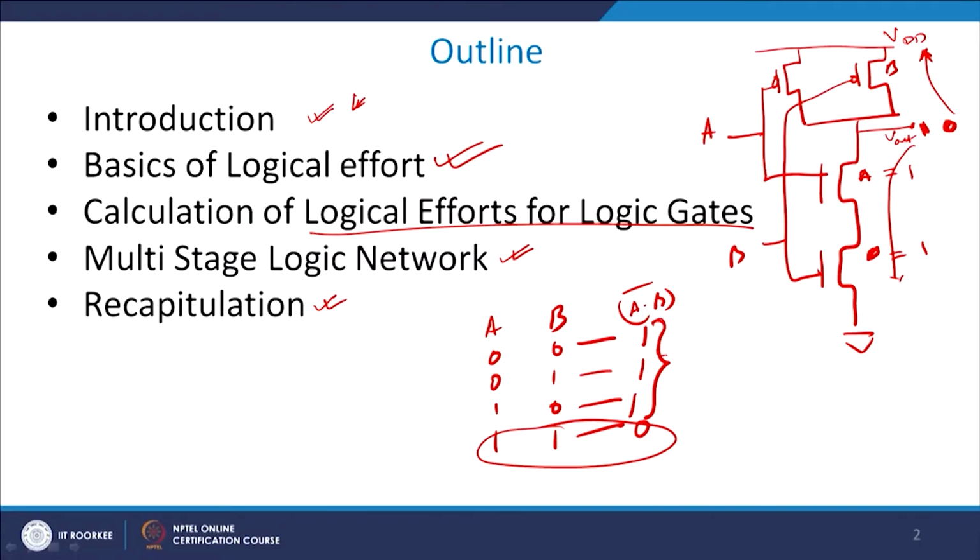So, therefore, if initially you have a data of 0 available with you, the probability that it will go to VDD is much higher as compared to it going down, assuming that all the inputs are statistically possible and independent with respect to each other. Then if initially you had 0 in your V out output, then it can go to VDD under all these 3 conditions, whereas it can stay at 0 only in one condition, which is basically this condition.